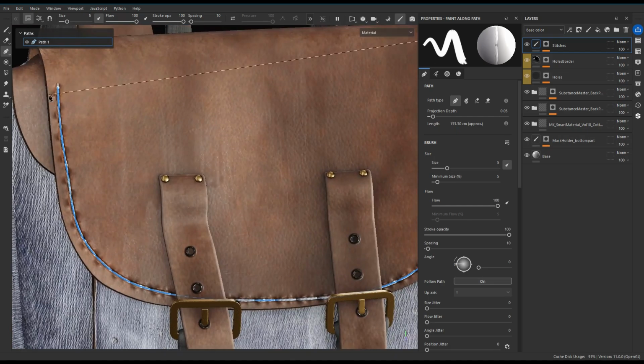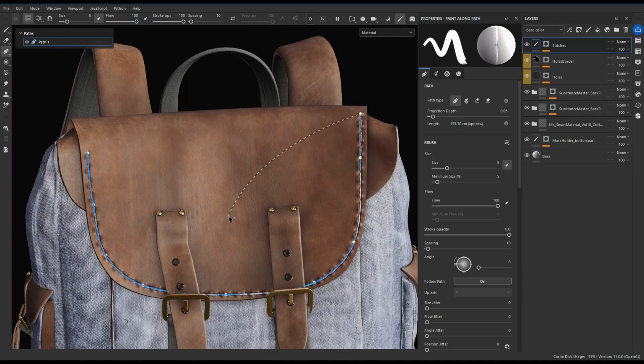So when you select this path tool, if you want to create a new line, you need to press escape or enter on your keyboard and just draw a new line. Okay, and if you don't want to see this line, you can just simply turn this off or on, or just use the Q on the keyboard. That's it. So I go here, choose this path, and I want to change it. You can do that. It's easy.